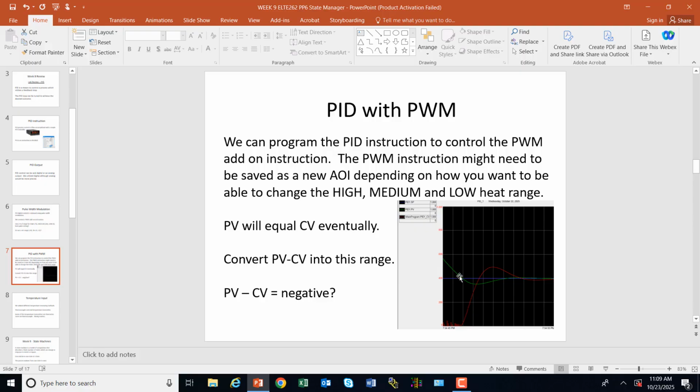And you notice it came down pretty quick, and it overshot. Then it came up, or excuse me, undershot, then overshot, and then kind of converged on this. Well, I also plotted my control variable. And it's not my full error, but you realize that the control variable is in error. It's different than what my PV is, but these are going to eventually reach each other, and you notice that my control variable overshoots and undershoots, and then it eventually comes back in, and they're equal.